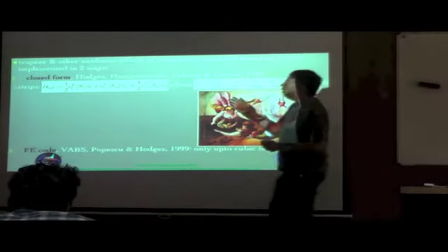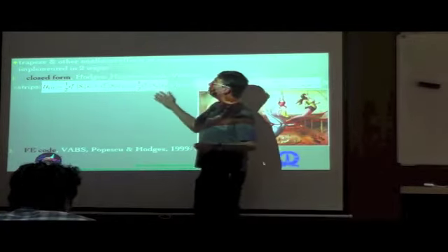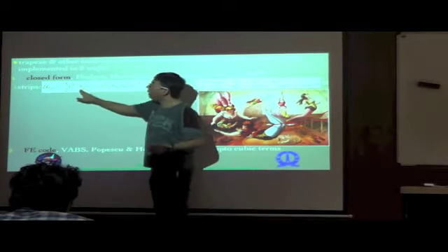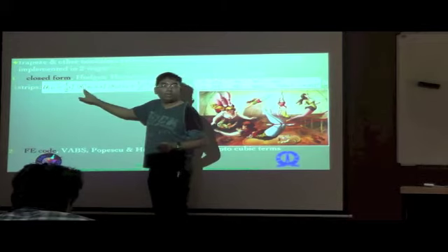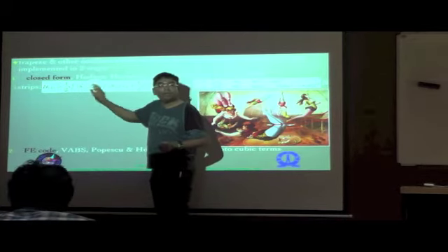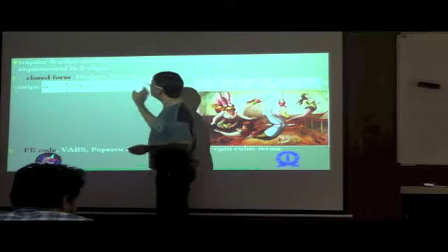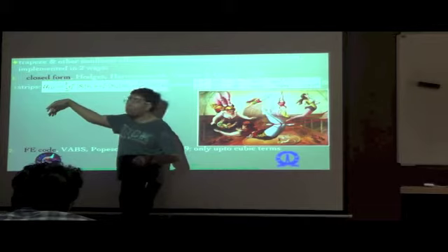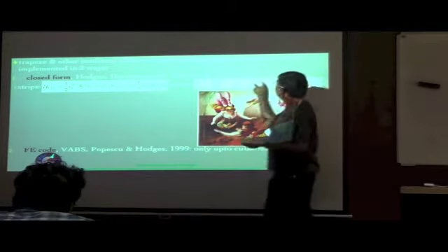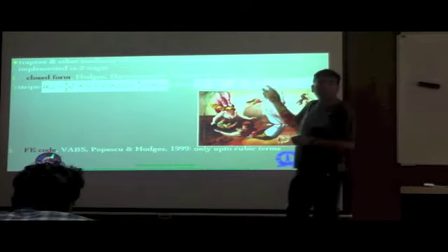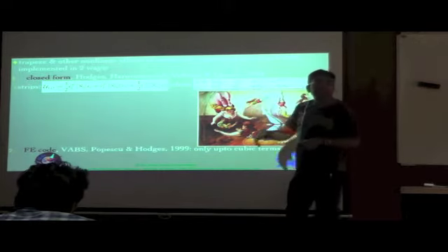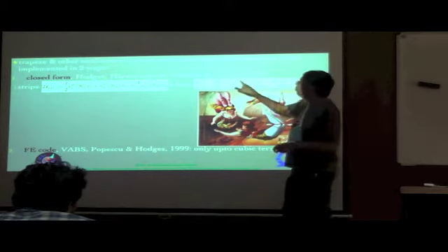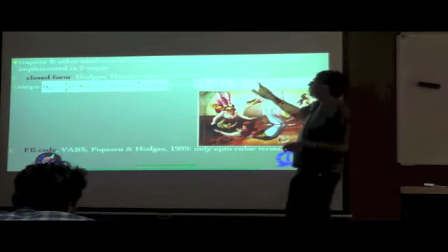And this is one way of expressing this particular relationship. You can still go back and express it just as this first term, but with this matrix no longer consisting of constant elements, but instead of functions. In other words, you can take the derivative of this u1t twice with respect to each one of these strains, gamma 11, kappa 1, kappa 2, kappa 3. The first time you take a derivative, you will get the forces and the moments.